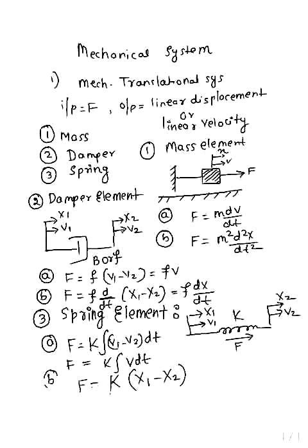First we will write the A part, the force equation in terms of velocity. So F is equal to spring constant K integration of (V1 minus V2) dt, or we can write directly K integration of V dt.